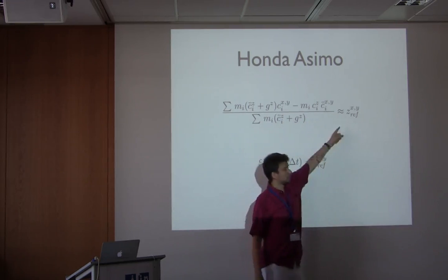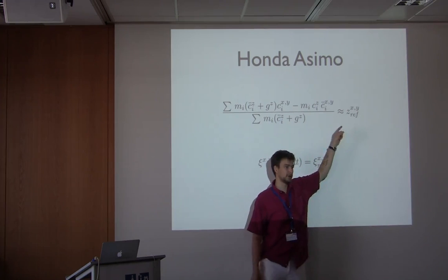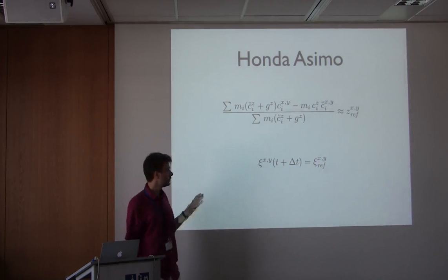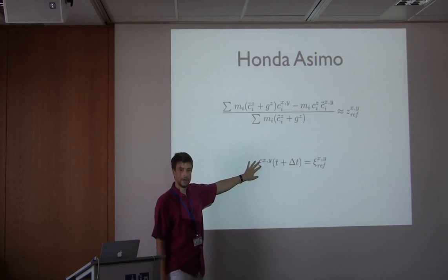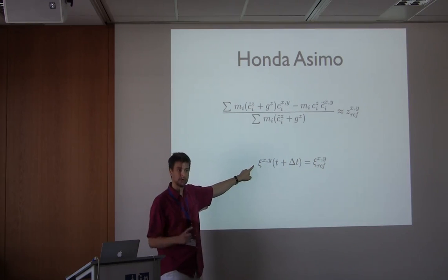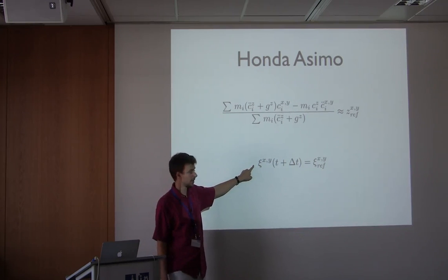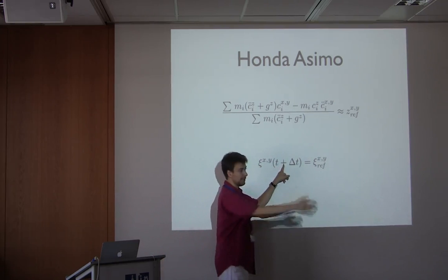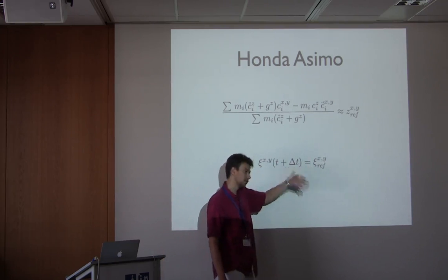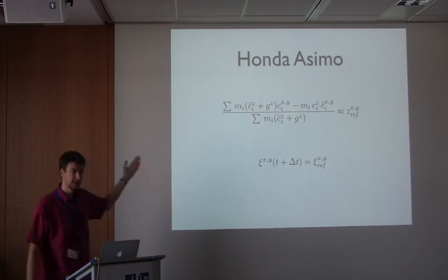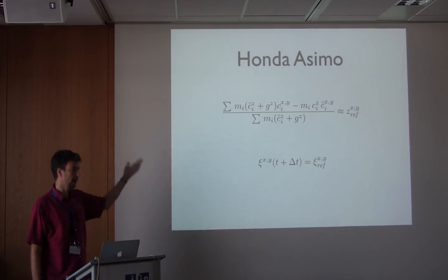They use a predefined motion, predefined footsteps, and a predefined trajectory for the center of pressure, except for 1 or 2 degrees of freedom, which are used to satisfy this constraint: the capture point, and this time they use the proper capture point constraint. The capture point, after a certain time, so here 2 steps later, should be here in the control position. Okay? And that's how they generate walking motions online for the Asimo robot.